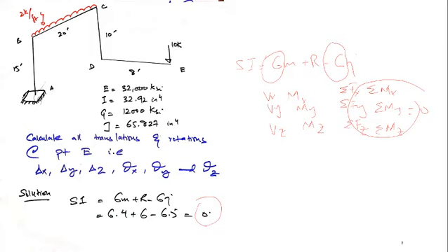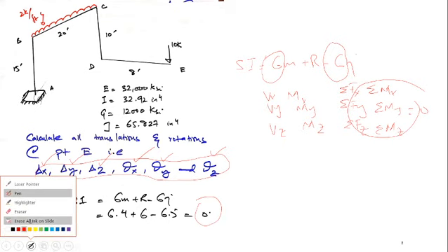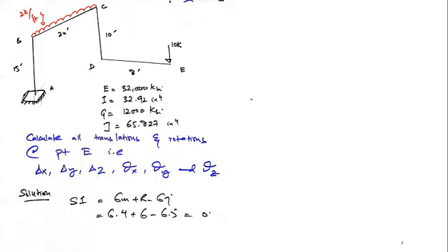Anyways, it's a determinate frame, so you have to calculate the translations and rotations in all these 6 parameters. Now this is translation in x direction, this is in y, and this is translation in z. This is rotation in x, this is rotation in y, and this is rotation in z. Actually, I have to show my frame of reference.